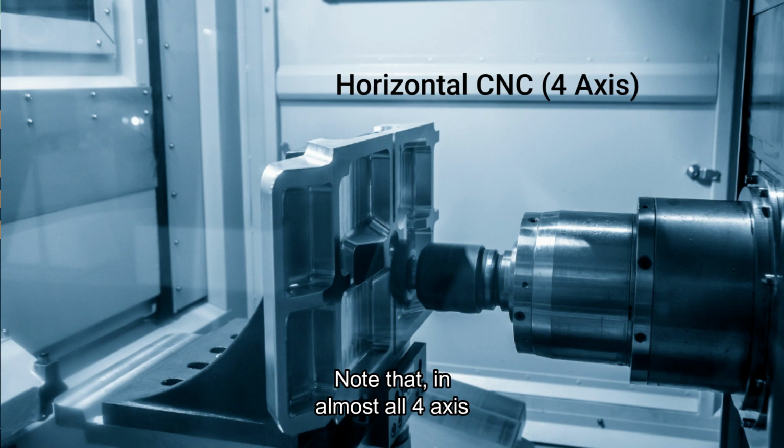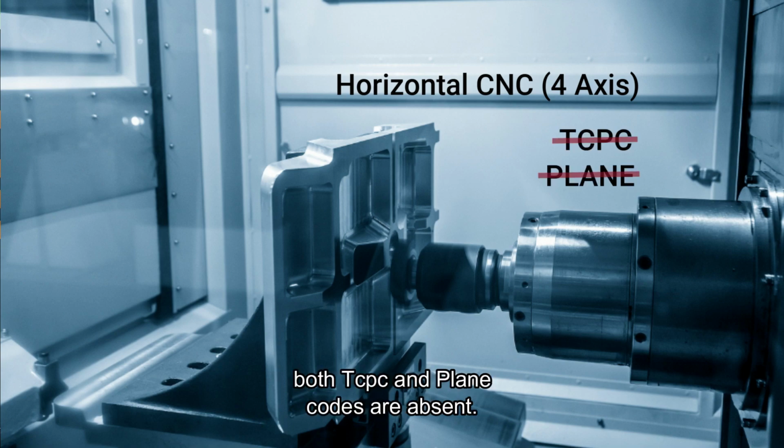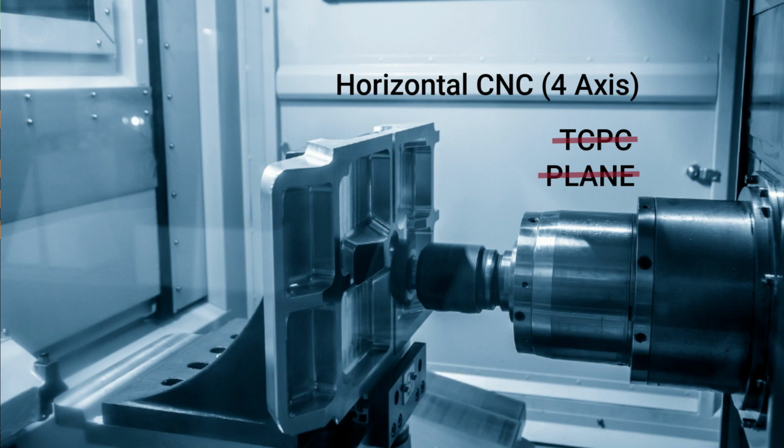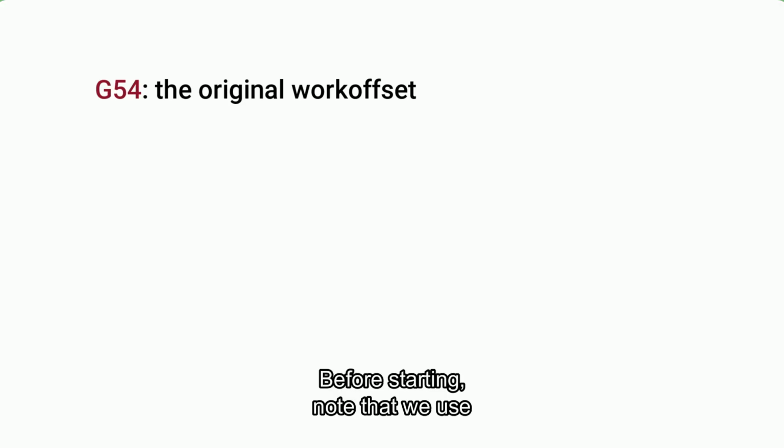Note that, in almost all 4-axis horizontal CNC milling machines, both TCPC and plane codes are absent. Therefore, I will explain the advantage of using our special post processor on 4-axis horizontal CNCs. However, keep in mind that these advantages are also valid for 5-axis CNCs without TCPC or plane codes. Before starting, note that we use 3 work offsets as default in this mode.